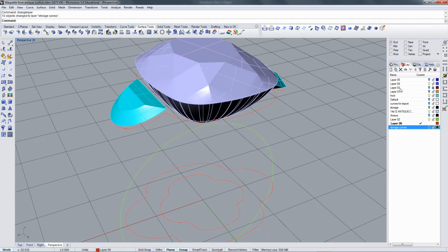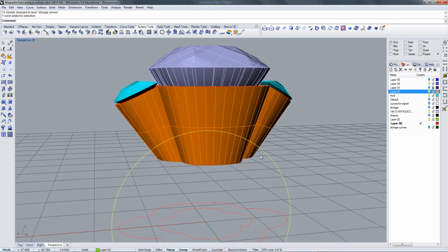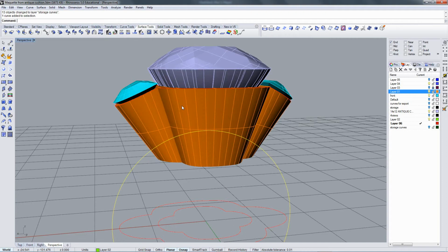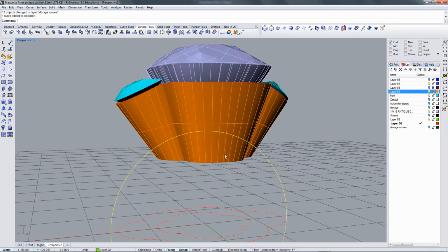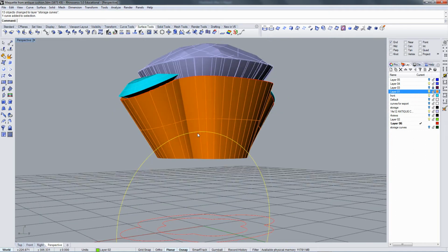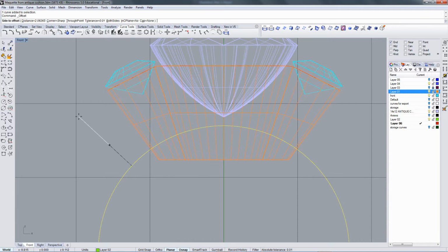So I have the main block. Now what I need to do is determine, I have already decided I like 1.5 millimeters here. I like that. And I have my finger bore there. What I did last time is I created a window box that would trim everything out. I'm going to do a little different thing this time. I'm going to offset the curve. I'm going to offset it 1 millimeter. And I'm going to do the scale just like I did last time.